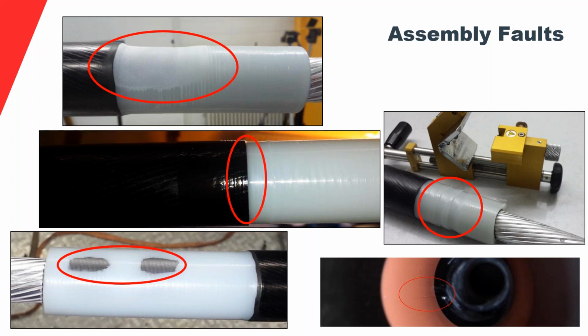Then down on the left, you see contamination, and then on the right you see that the cutting tool slipped off and pretty much cut into the main insulation. So all of these things and many more, bug infestation, we've seen many things, and all of this will be visible during a PD test.